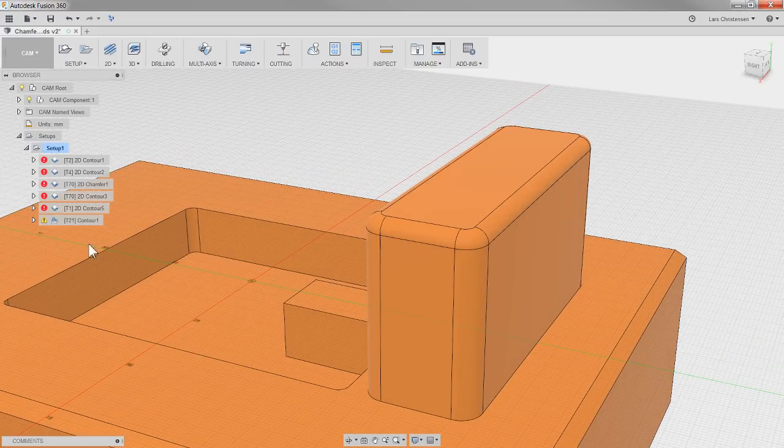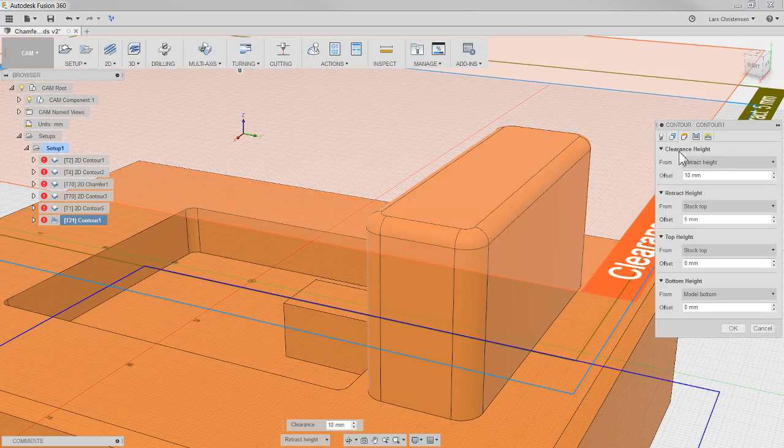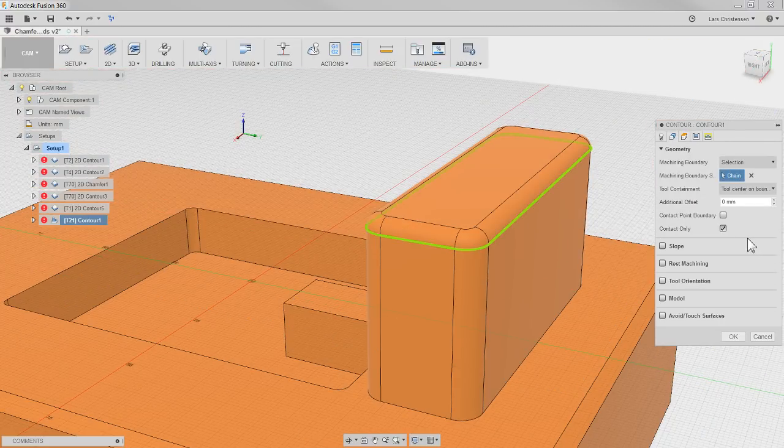What maybe could be a little bit worrisome, why is it not going to machine anything? Well, I wanted to do this just to give you a chance to explain this in here. So the contour toolpath we're using for 3D is really trying to look for vertical walls. And if it doesn't see any vertical walls, you can't put any toolpath on, it's not going to do it. Again, the development team doesn't want to gouge your part.